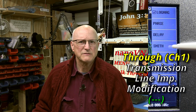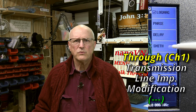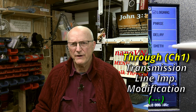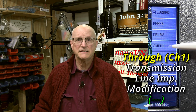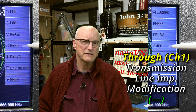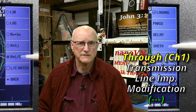The equivalent transmission line impedance modification as we move along the transmission line from channel 1, the load, toward channel 0, the generator, clockwise around the Smith chart. It is in this direction because this is the value as viewed from channel 1, the load's perspective. This can be expressed in terms of normalized polar coordinates, resistance plus reactance, or resistance plus capacitance/inductance.